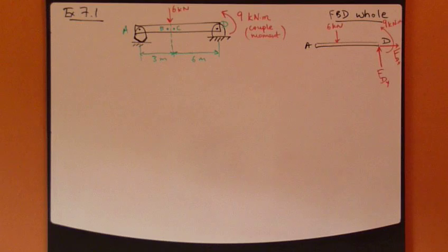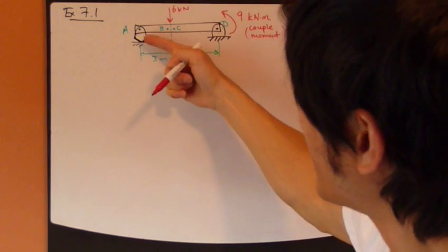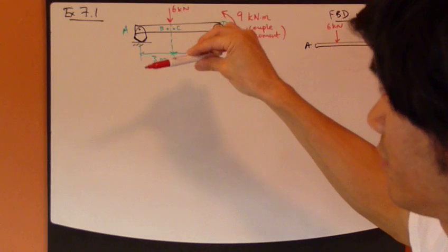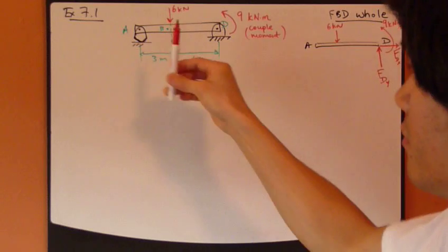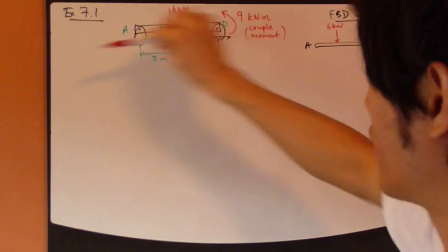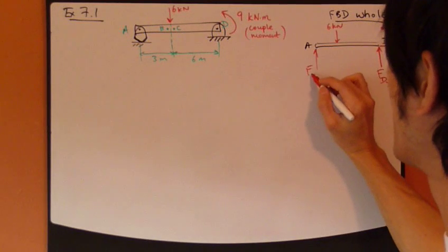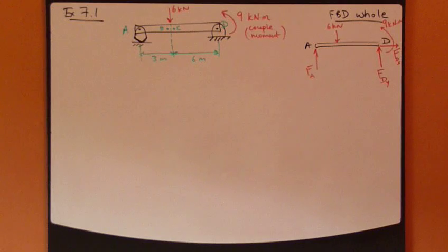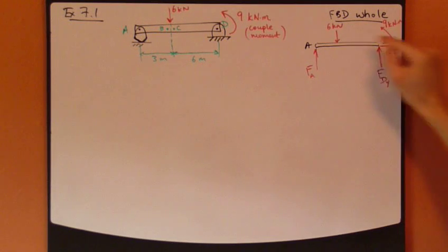FDX. What else? Well, this point A. Now, this A is just simply resting on the ground. So, there's only one reaction force, which is perpendicular to the ground direction, which is this way. So this is my reaction force at A. That's it, just one component, a vertical component. Alright, so this is my free body diagram for the whole rigid body.